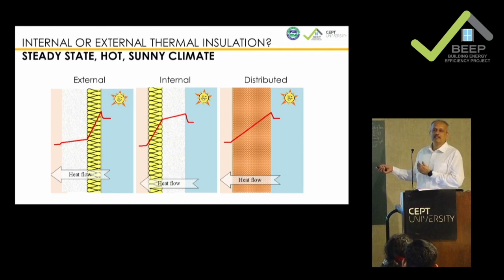This is what exactly happens in the Jaisalmer Havelis, where there are such thick walls. In terms of theory, they are insulating walls, right? So heat comes in, they keep absorbing heat, but before the internal surface temperature goes up, outside temperature drops, and it starts going out.